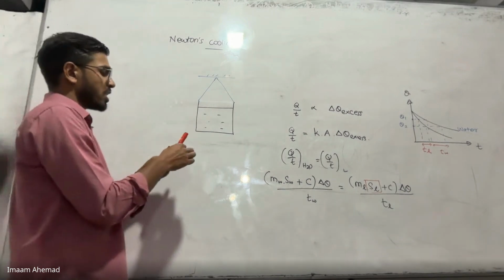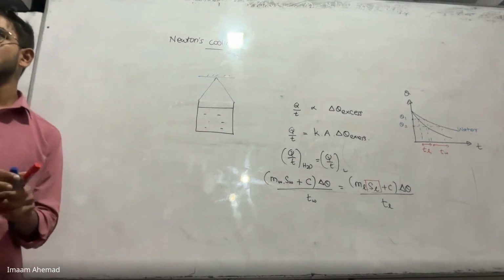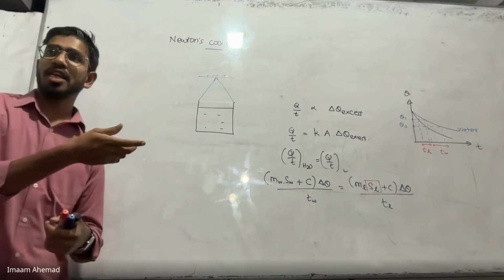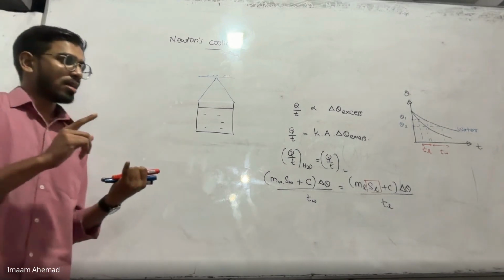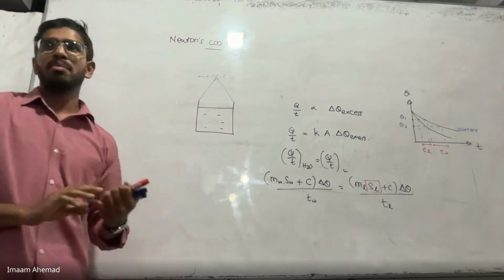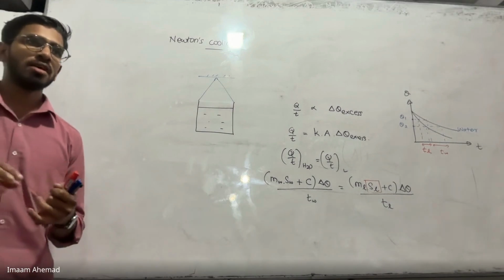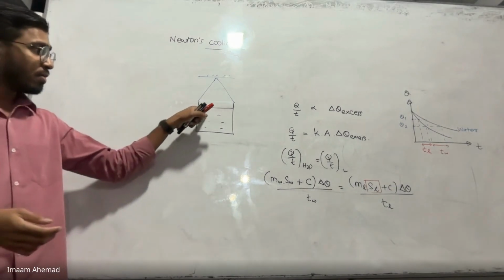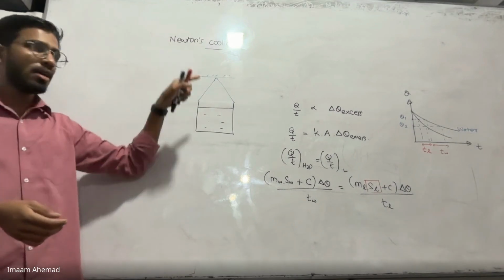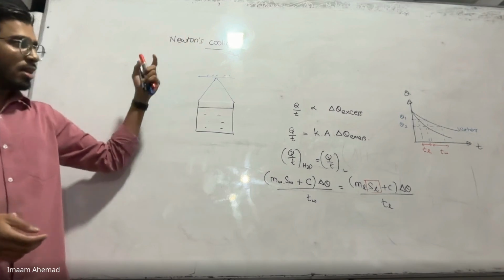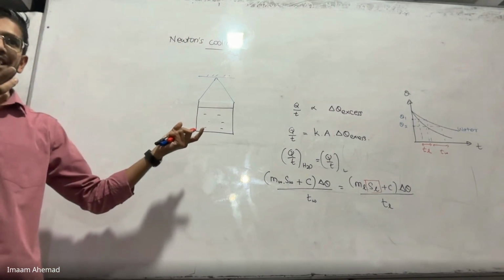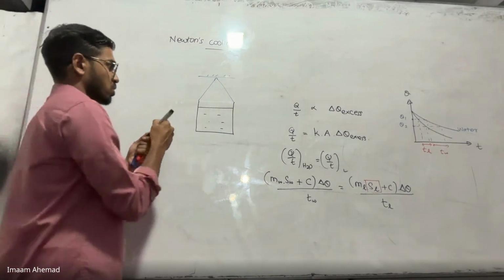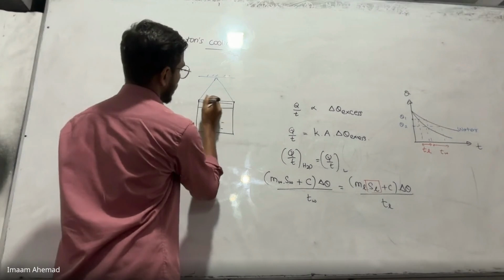Then what about using a lid? Do we need to use a lid over here? Why do we need to use a lid? What's the purpose? Conduction energy loss we reduced by hanging it. Radiation also we reduced by using a polished calorimeter. Then why do we need a lid? Water can evaporate, right? Water or the liquid can evaporate. If it evaporates, then the mass we measure and the heat it has, all of them are going to create error because they are escaping from the system. So to minimize that, we can put a lid.